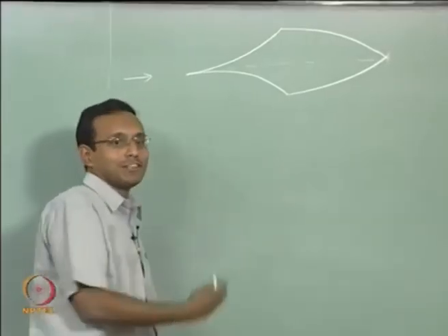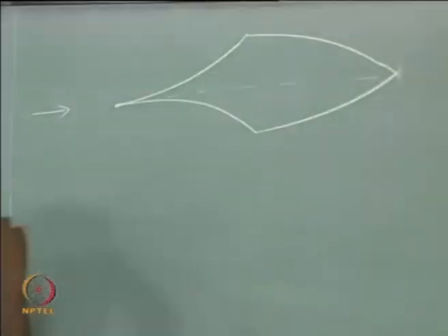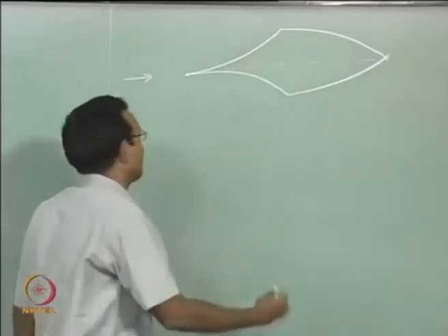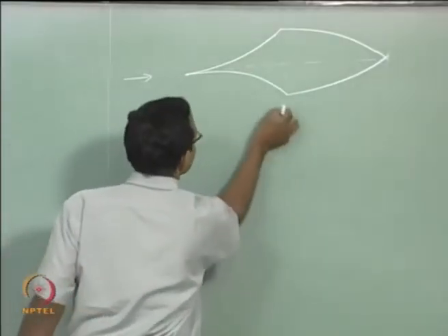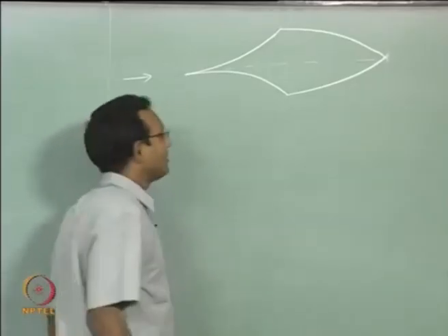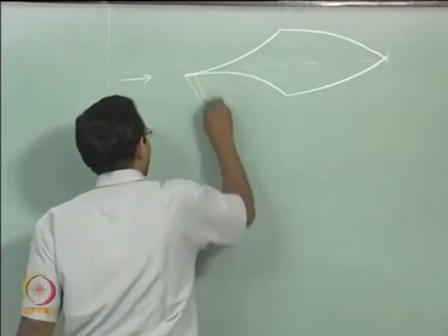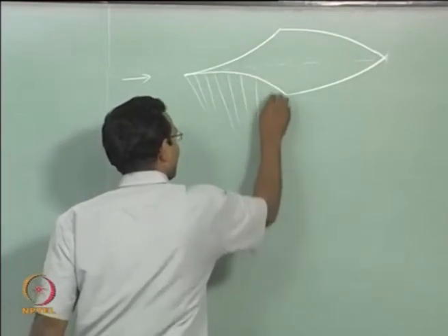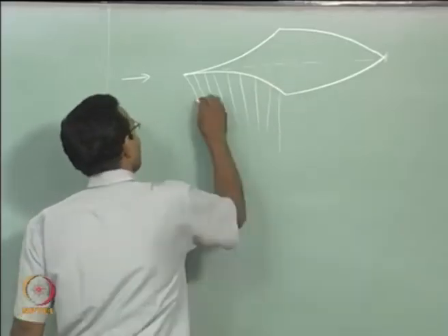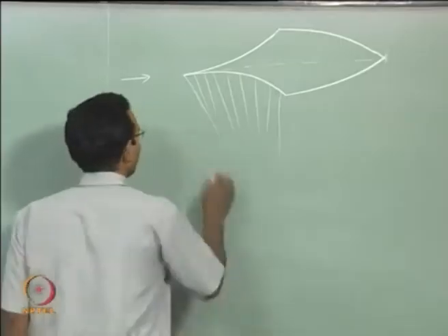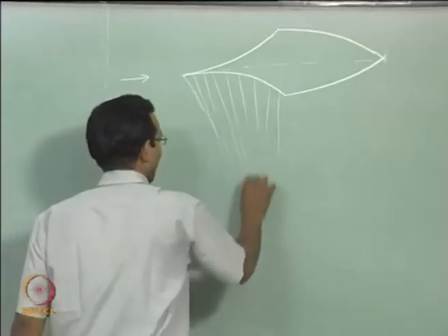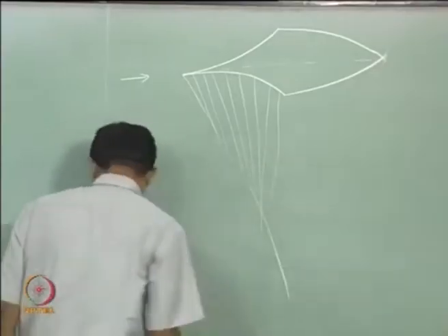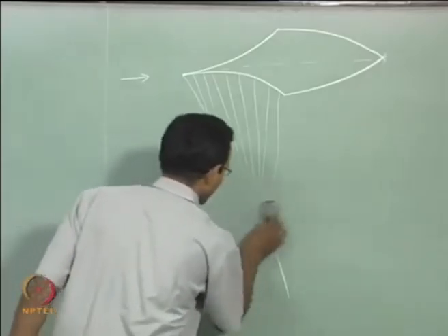Again I am going to use shock expansion theory here, the craziest airfoil. Since I am saying it is symmetric and I do not have top space in the board, I will look at only the bottom. It is a smooth corner transition, smooth compression. So I am going to have a set of Prandtl-Meyer waves which are coming out from here, and I already told you that these waves, since they are all compression waves, they will all get together eventually to form a shock here. But let us not worry about that right now. It is not coming from shock expansion theory.